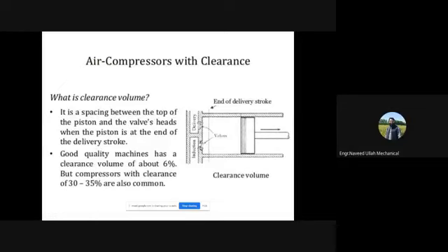राइट. सो द कंडीशन फॉर मिनिमम वर्क की समझ आपको आ गई कि भाई इफ यू वांट टू decrease the work consumed by the compressor that actually we want, okay, in order to increase the efficiency. There are different possibilities, but some of them are not practically possible, okay. As far as the indicator diagram or the PV diagram is concerned, we can do alteration over there. We can decrease the length of a line. You can take the line P2 down there, but they are not practical, right?